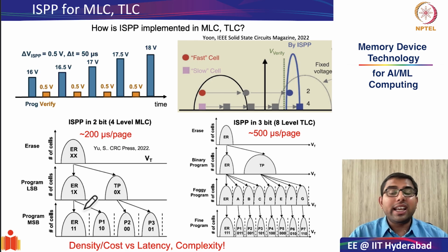We saw how bit scaling is done in modern day NAND flash by programming intermediary threshold voltages. Basically, we can fit in more bits by having several threshold voltages in the same physical cell. This can also be called bit scaling or logic scaling. We also saw three different kinds of NAND flash cells: MLC, which stores 2 bits, TLC, which stores 3 bits, and QLC, which stores 4 bits. What I hear is there is a lot of research happening for 5 bits and also 6 bits.